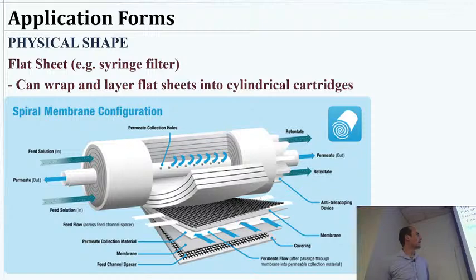You see this in the picture here. And you notice when I say the fancy plumbing, there are spots where water can make its way through the interstitial spaces. They've got little separation things allowing water to flow. And then anytime you cross one layer of a membrane, it's collected and it spirals its way down into the center of the module rather than traveling.